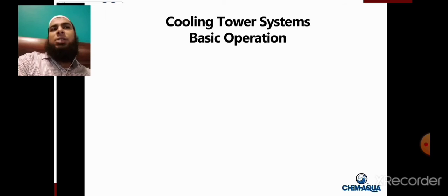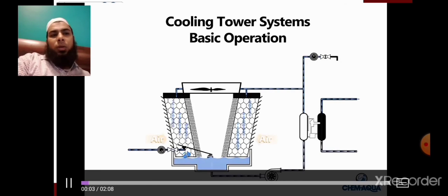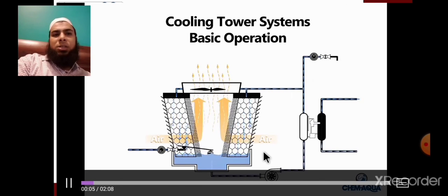If your site is situated near sea level, just like in Karachi we already have very high humidity, so the cooling tower will not perform very well, because it will not evaporate much water and will not reject much heat. But if it is placed in Quetta or very dry places, it will work very well. In a very short time a lot of heat is released from the condenser water. Okay, this is basically an animation and video of a cooling tower.